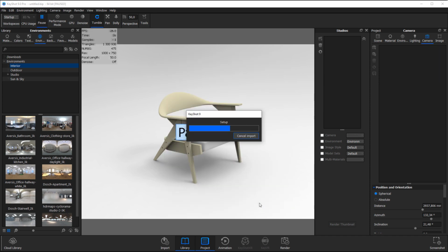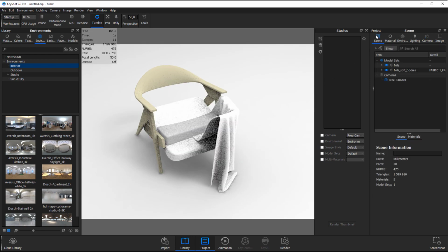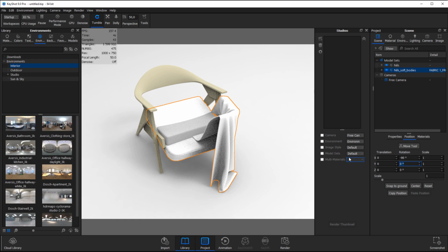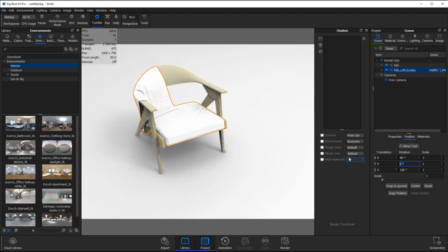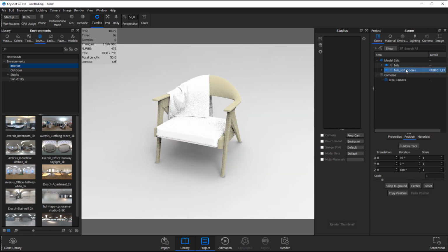Now, most of you will notice that the position isn't dead on as you import, and that's always a puzzle to figure out why that is. But as long as you kept the same units in all the modeling and the position is roughly the same, it's just a matter of rotating the soft body to make it snap into its right place. In this example, all I have to do is rotate the soft body 180 degrees about the y-axis. So now we're ready to dive into rendering.